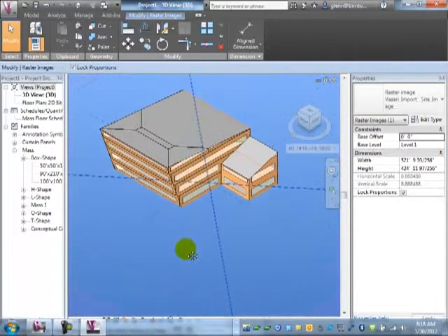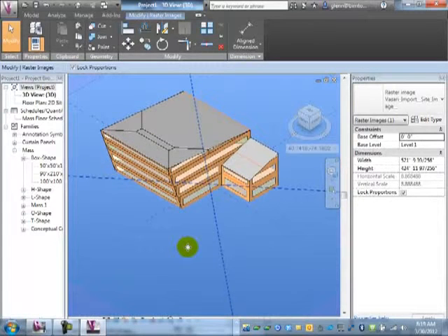At a very high level, you could look at the building this way. What it's done is it's said, given those floor levels and this size of the building, if we say there was a certain percentage of glazing to solid surface on each of those different building surfaces, this is what the building might look like. At a really high level, we're doing it the 10 minute way. This is probably okay for the type of analysis we're going to do to compare alternatives. You can always go through and adjust these things though.